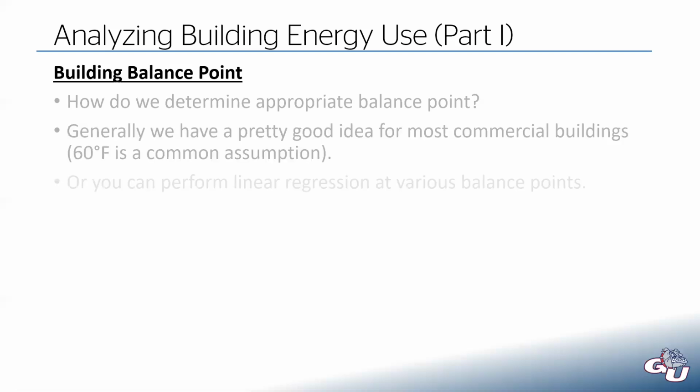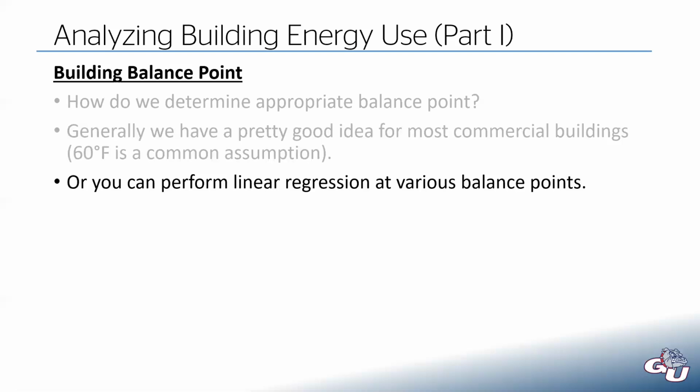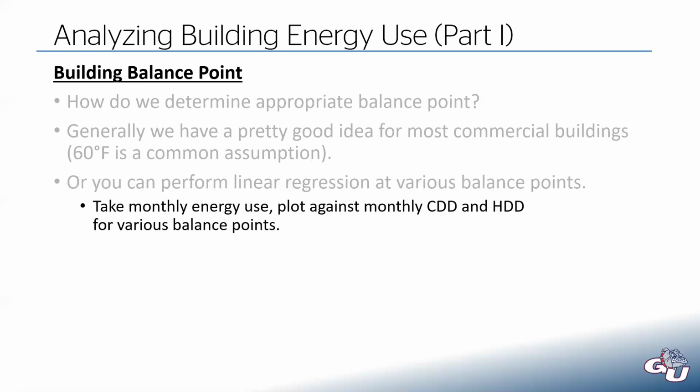If you want to get a little smarter about it though, rather than just doing an assumption, what you can do is perform a linear regression at various balance points, which I'll have some slides here in a moment that hopefully illustrate this a little better. But the general steps are you take the monthly energy use, you plot that against the monthly degree days at various balance points.